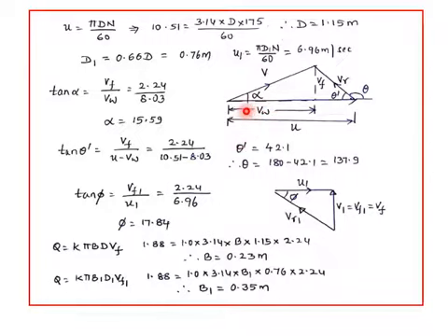So first thing is that here we know that U is around 10.51, and also Vw is calculated, which comes to about 8.0. Here in this case specifically U is greater than Vw. So now you know that V is this, so U starts from here, but since U is greater, it will cross this line and come towards here. In the earlier cases and all the problems we solved, U would stop here, U was always less than Vw. So this was Vr and the angle theta was this. But in this case the angle theta will be obtuse.